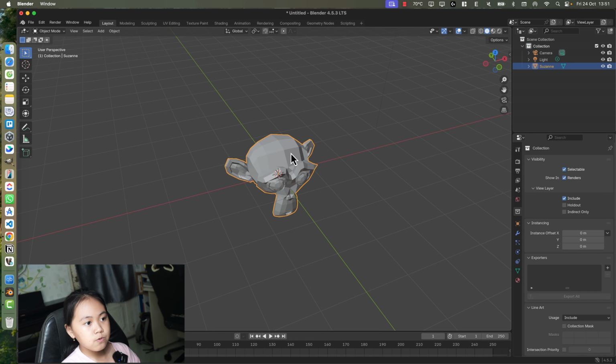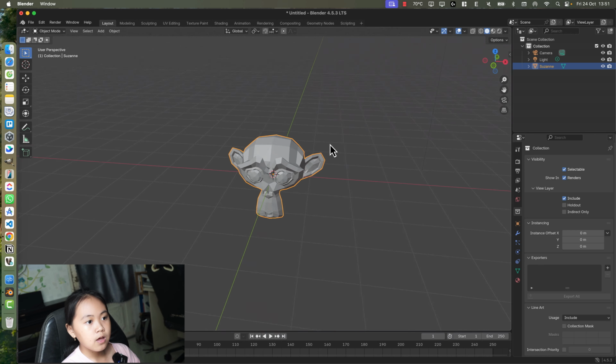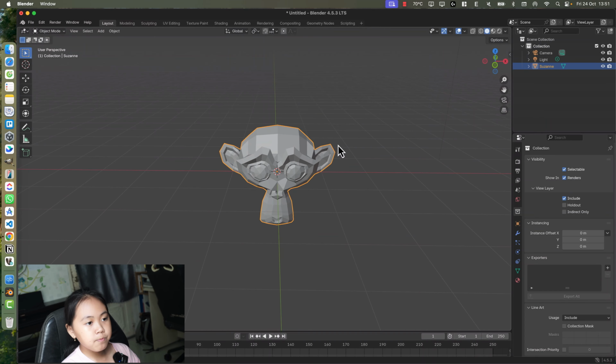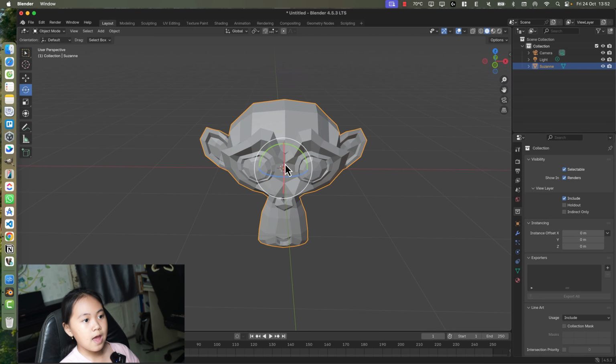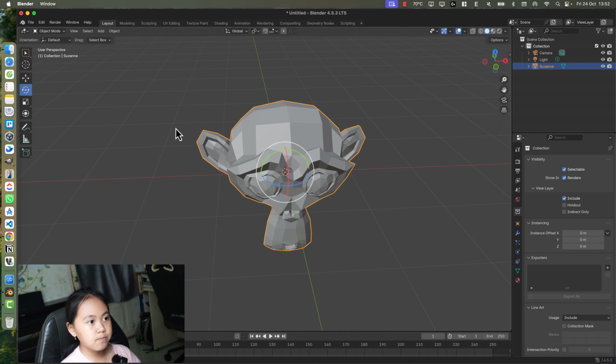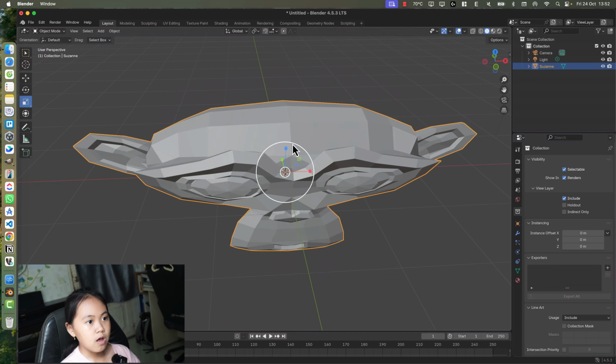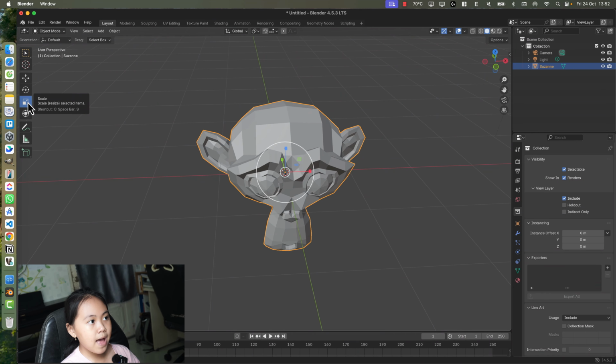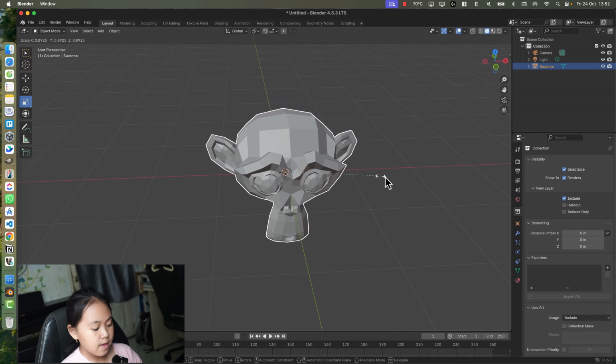let's learn undo and redo. How do we do it? Well, with most programs, you can undo and redo, which what undo does is basically move to your most previous, latest action. So, for example, I'm just going to scale it. Okay, for the rotate, I forgot to explain the transforms. The rotate will help you rotate. Real simple. The scale helps you scale. Also real simple. And you can use them all by the shortcut, which is shown, which is S for scale, and R for rotate. So all of them work the same, and they also lock axes.